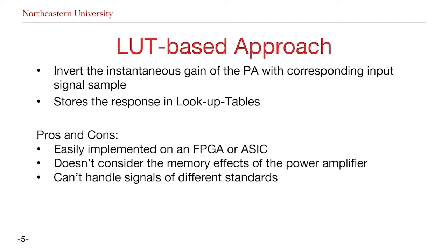This actual mapping relationship between the input and its response is stored in the lookup tables. Although it's hardware friendly and people can easily implement it on FPGAs or ASICs, it does not account for the memory effect. And similarly to the previous approach, it only handles one signal standard, and it requires re-describing the model when changing to different signal standards.